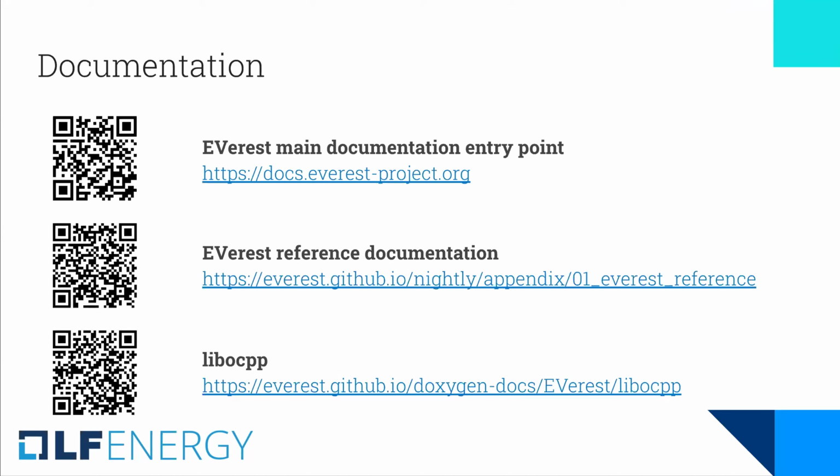Perfect. Their next question was about safety, but we covered that on a previous question. The next one is, does EVerest support integration with energy metering ICs, such as the ATM90E32AS for power and energy monitoring? I think not for this specific module, but we have basically all the interfaces that are needed to write a driver for something like this.